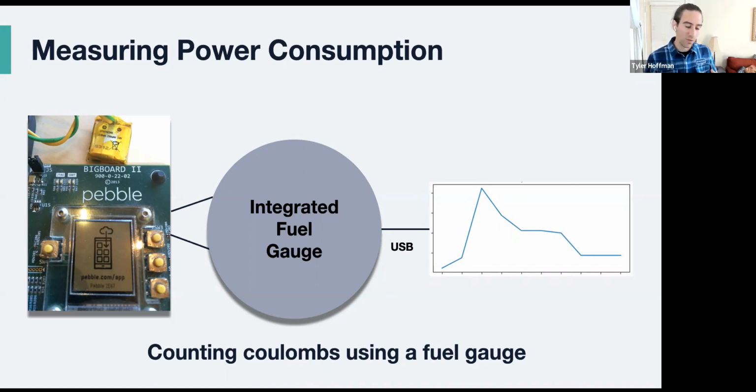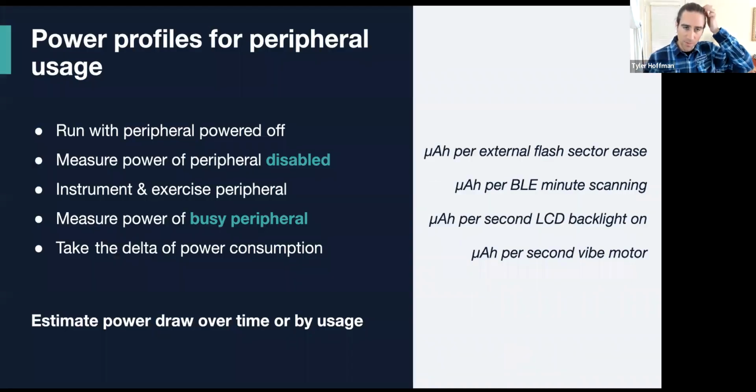But for those who don't know, a fuel gauge is connected between the system and the battery and can count exactly how much current is actually drawn from the battery. So ideally, you could just do the simple math locally and give an accurate percentage of how much battery life is left. But you can't do that remotely, again, because many people don't use it. So we can collect metrics on the other end, but first we're going to come up with a battery model.